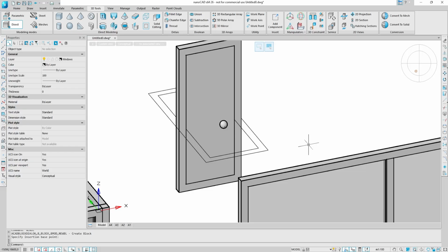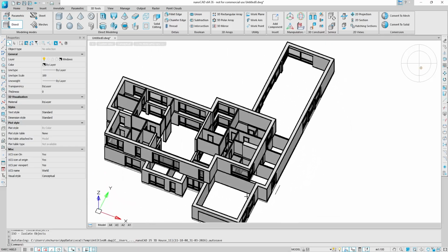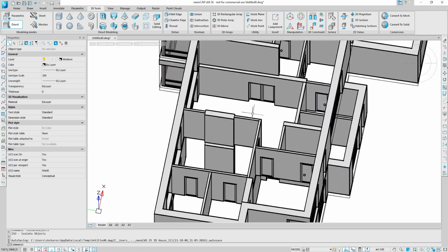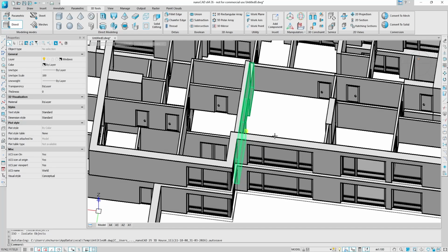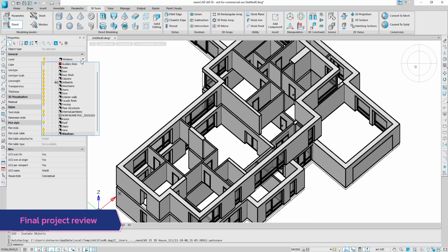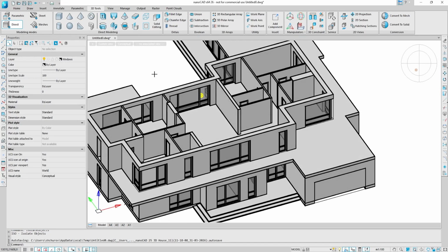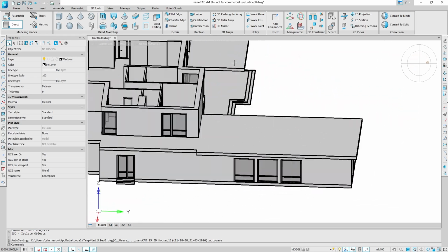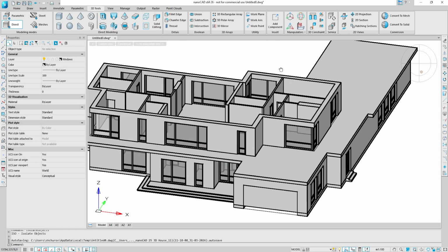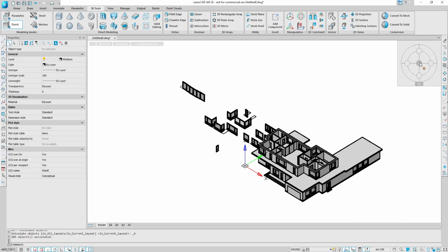Insert all the doors into the interior walls yourself. After inserting the doors, the results shown in the video should be obtained. Turn on the display of the floor structures and stairs layers and take a look at the entire project. The blocks in the project can be deleted, as they are easily accessible through the block insertion window.